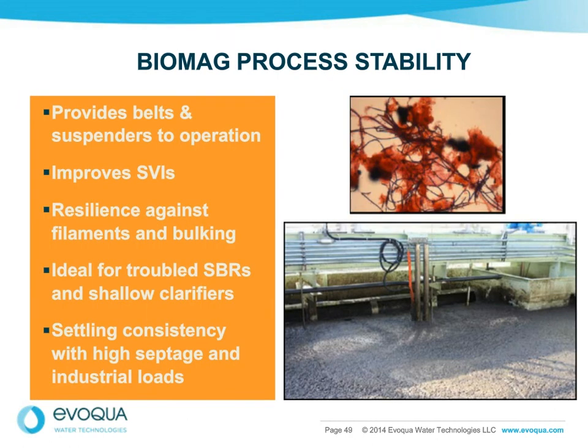Now, one of the things with BIOMAG is adding stability and more robustness to your biological process, and overcoming those things that I like to call cumbersome or bottlenecks to the activated sludge process, filaments, etc. And the ability to do that not only in a conventional activated sludge, but very commonly with SBR processes or shallow clarifiers where solids don't want to readily settle.